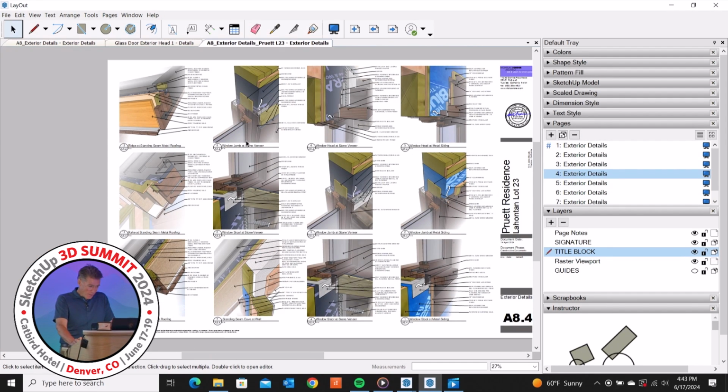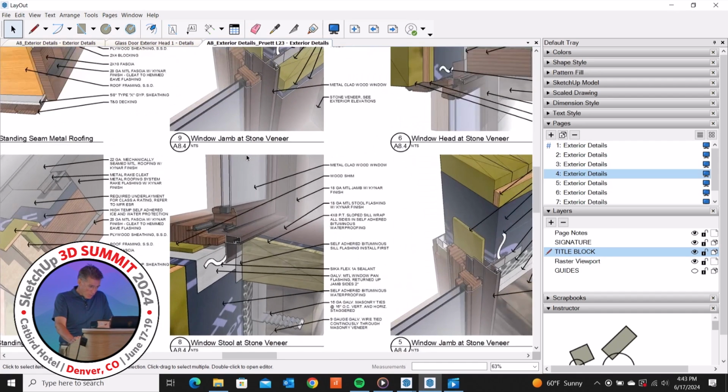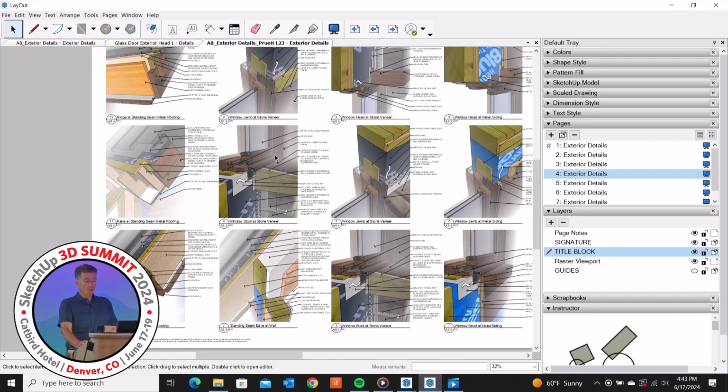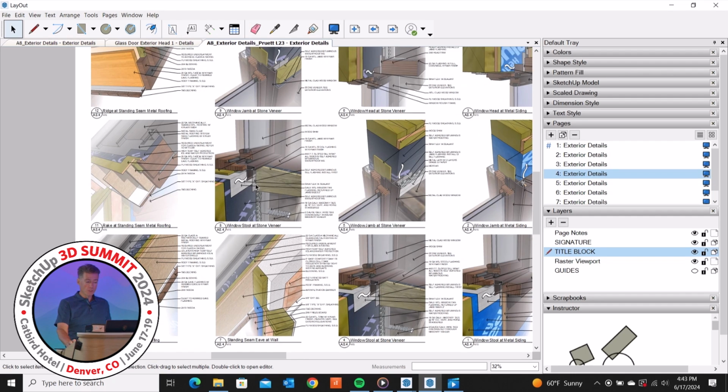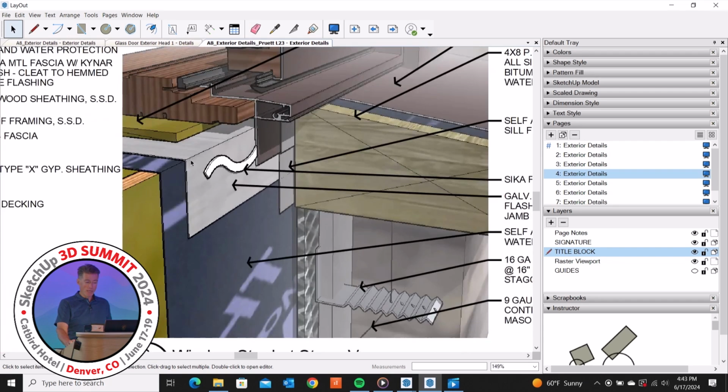And then this last one, I'm trying to see why this was different. Oh, this is one where we had a very special condition where we brought up a really high wainscot of stone, and then it transitioned to wood siding above, and then we did a metal sill and completely covered the slope sill. So the sill shows it, and that actually shows that pan flashing that 9 times out of 10 nobody installs. Does everybody install that where you guys are? Yeah? Do they actually install it?